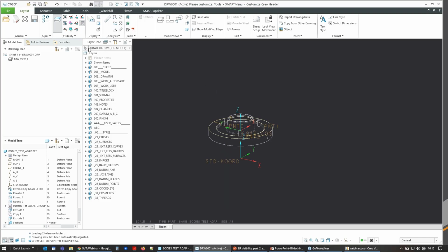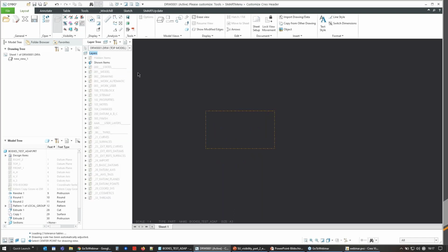And now I just hit this little arrow button to show up the boundary. So as you see, this is a brown boundary, and this means this view is drawing dependent and it follows the drawing settings of this drawing. So if I want to correct this all, this is very easy. I hide everything in here. And from there, I'm just using this one, isolated, and my display gets corrected quickly.